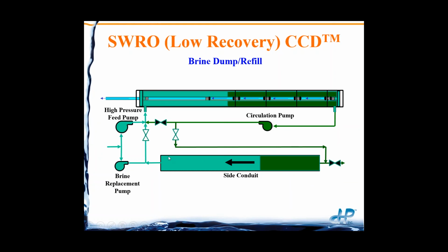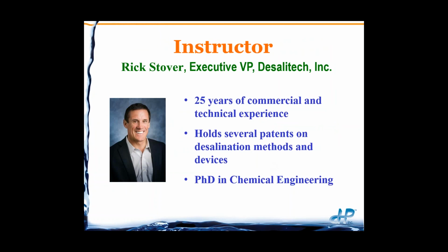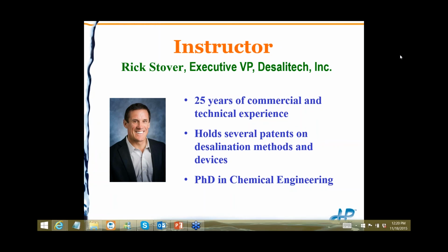Once the brine has pushed all the feed water out, now we're back in closed circuit mode, and now the feed water is going to push the brine to drain. So very similar to a positive displacement energy recovery device. Okay, so that's just a rundown, an introduction on CCD. Now Rick is going to give the bulk of the presentation, the details of CCD. So we're going to change presenters, and Rick will come on in just a few seconds.